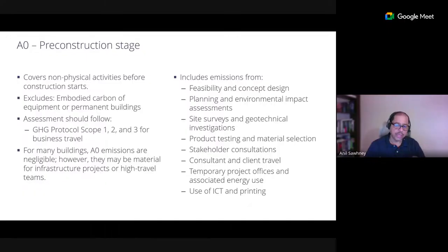So we need to calculate A0. The emissions that come from, as I said, site surveys, geotechnical or other kinds of investigations. Maybe you have soil investigation that requires heavy diesel-operated equipment, emissions from that, all your site meetings, team meetings, and all other aspects of emissions during the pre-construction acquisition stage, generally for infrastructure projects, are included in this A0 submodule of Module A.